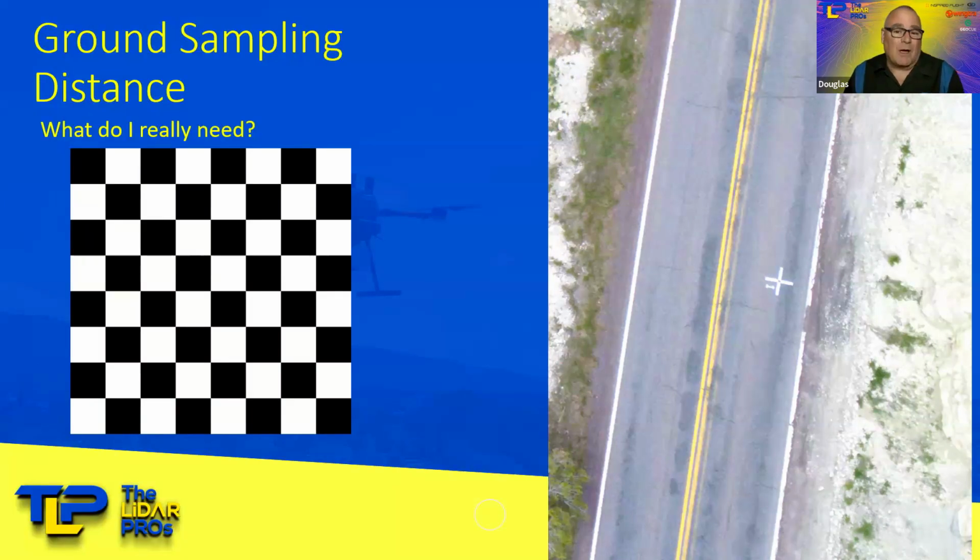It's a good idea to try to see if we can achieve somewhere between half a centimeter per pixel all the way out to 2 centimeters per pixel. Anything higher than that in a low resolution camera format, such as these 20 megapixel 1-inch cameras, we can run into some challenges, unless we're just doing gross work and we're not worried about getting down to our 0.2 of a point in accuracy, or a centimeter of accuracy. So think about what that ground sampling distance really means.